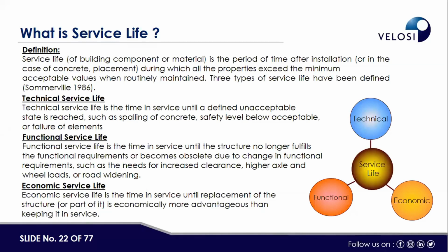The answer is no. Design life is based on the limiting components or bottlenecks, the components of the facility which may get retired or may have certain damage mechanisms active. Because of the defects caused by the active damage mechanism, we may have to replace those components. But if we replace those components, the life of the whole facility can be extended further. Like in a turbine, an engine, or a pump, if weak components, starting from casing to impeller, impeller to bearing, bearing to other parts, are replaced when their good life has expired, then the life of that particular equipment can be extended further.